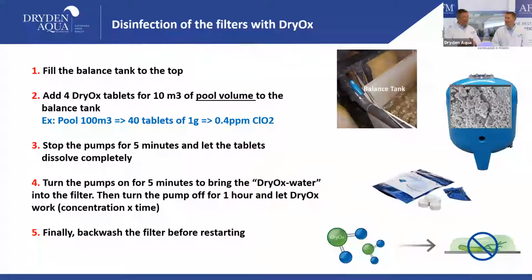What happened yesterday night? I think this is not good if you don't drink enough, it's the chlorine dioxide. Yes, maybe. But the chlorine dioxide water has to come really into the filter, to the bottleneck, to the nozzle plate, or to the laterals, and then the best is you stop it and let it work. This is the CT value, concentration with time. Disinfection is always a function of concentration, the higher the concentration, and the time you let the disinfection work on it.